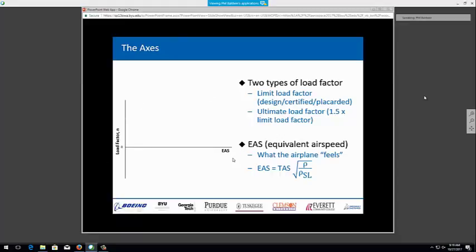So this comes out to be linear lines that start at n equals 1, with a 50 foot per second, 25 foot per second, plus and minus. These begin to define other limits on the loads that you can have. So we can calculate the intersections of BC and BT with the loads, and these will then decide whether we're being limited by the gust load, or by the dive speed, or by a maximum load factor.